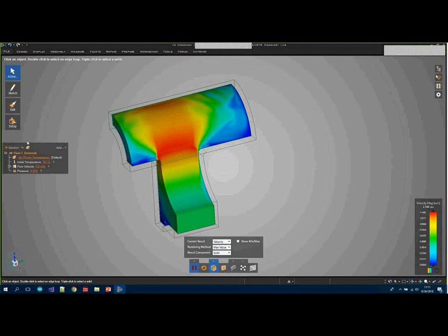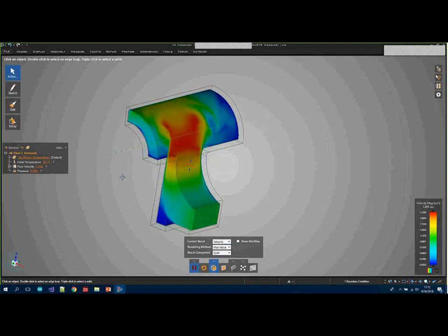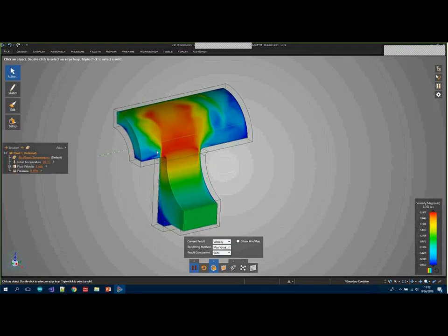Currently in our solution, by default, we selected air at room temperature, which is 20 degrees Celsius. The flow velocity is here. It's currently set to 0.5 meters per second. We can increase that if we want to. Maybe I'll set it to 1 meter per second. And you can see that it begins to update nearly instantly. There you can see our maximum velocity highlighted in red.